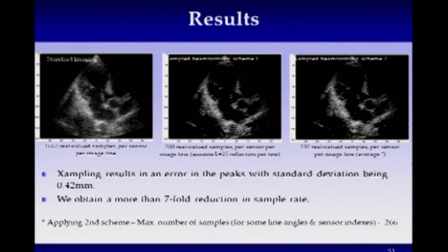Here we're sampling at about a 10th of the Nyquist rate, which is nice. But what's more important is that all the beamforming is done at that rate. So the savings is that 10th to the power of the number of arrays times the number of pixels at which you do the beamforming. So there's a huge savings here in terms of the DSP.